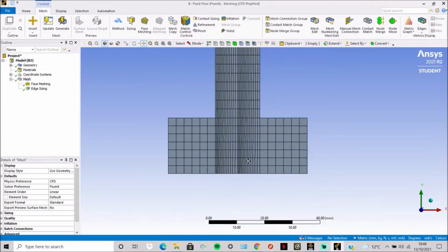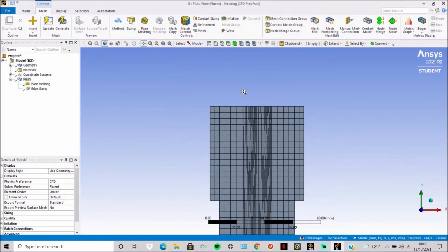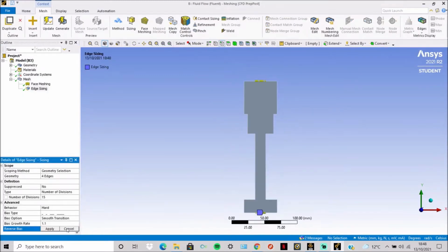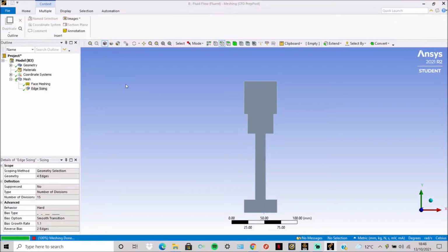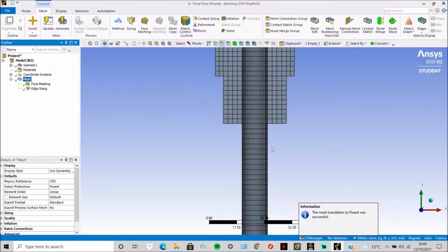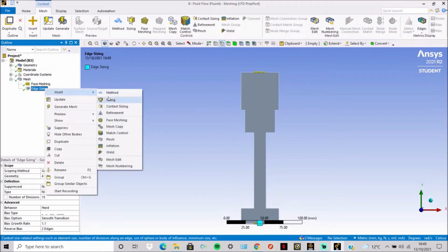As you can see, it's dense and then smooths out, but we want it dense and then to smooth out in the middle on both, which means the left top and bottom right will need to be reversed. Like so. We'll update. And now the mesh should be dense on the outside and smooth on the inside. We will now repeat this process for all of the edges.